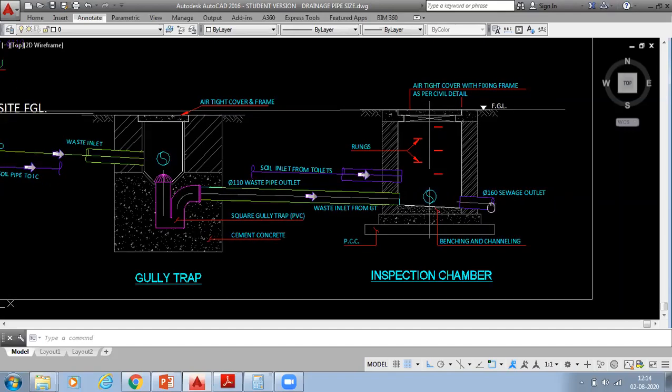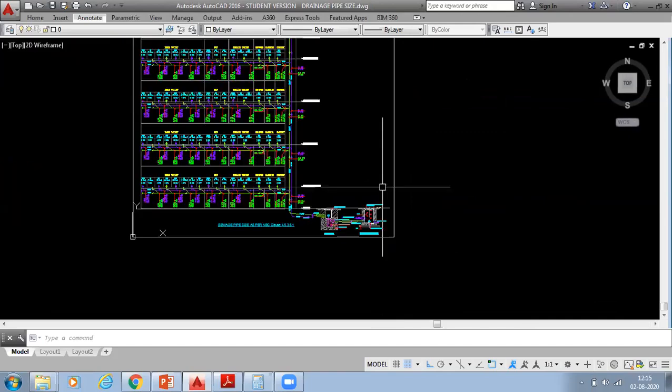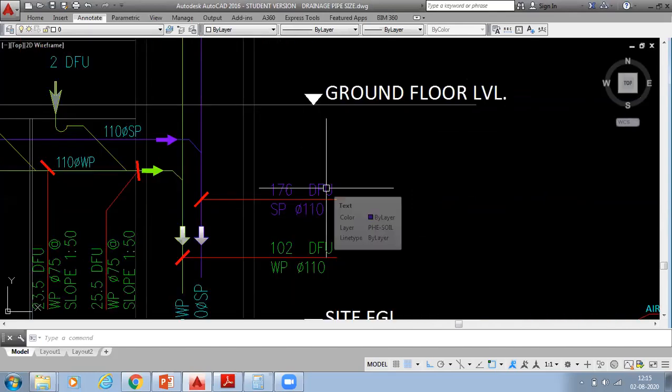After that, if you have more buildings connecting into the same manhole or same network, you have to calculate based on the flow rate. You can get the flow rate from the fixture units. That I will tell separately, when I explain the water supply pipe calculation: how to get the flow rate from the fixture units. That is all in our NBC calculation.